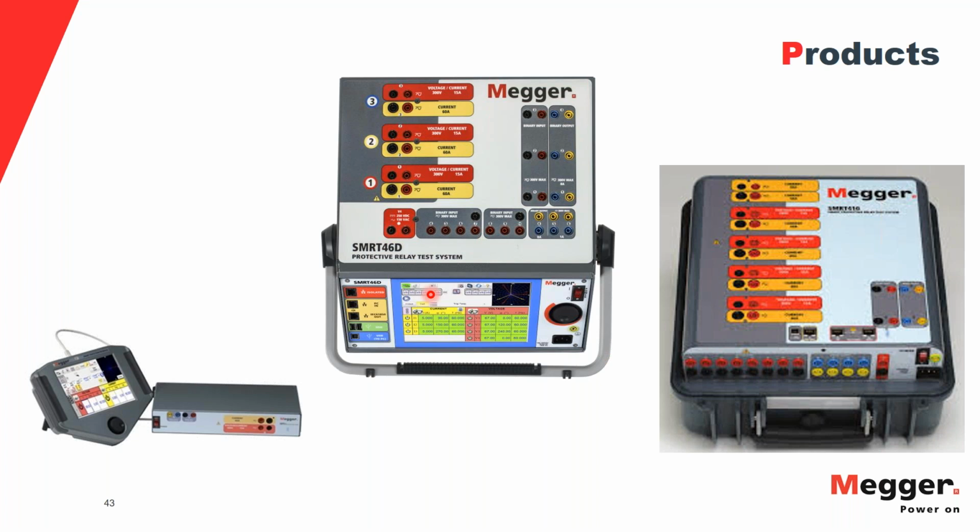The good thing about the D units that we have is whenever you connect the D units with the PC, the software in the PC takes control, and the onboard display turns into a meter. So you can actually check the metered outputs from your current and voltage. It's always a good practice to see what values the test set is outputting, the magnitude of current and the phase angles. Once you know that, it becomes really easy to troubleshoot some of the testing dilemmas.